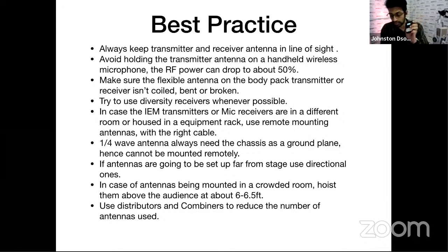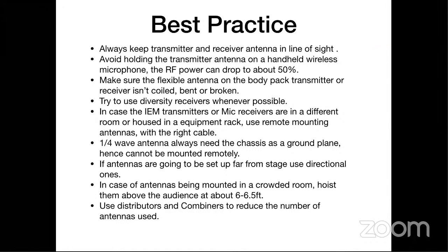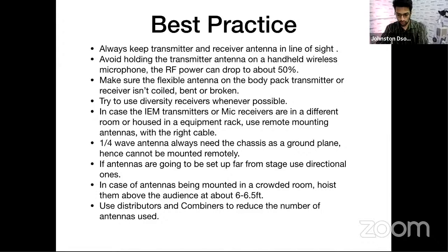470.1 megahertz, and say I have tuned an Axient system microphone to that, and a reporter comes in with this kind of a wireless system, and he's also tuned to the same frequency. The Shure system is smart enough to find out that the other Sennheiser system that has come in is not a part of my system, because the mic transmitter and the receiver have a signal that is encrypted in them.